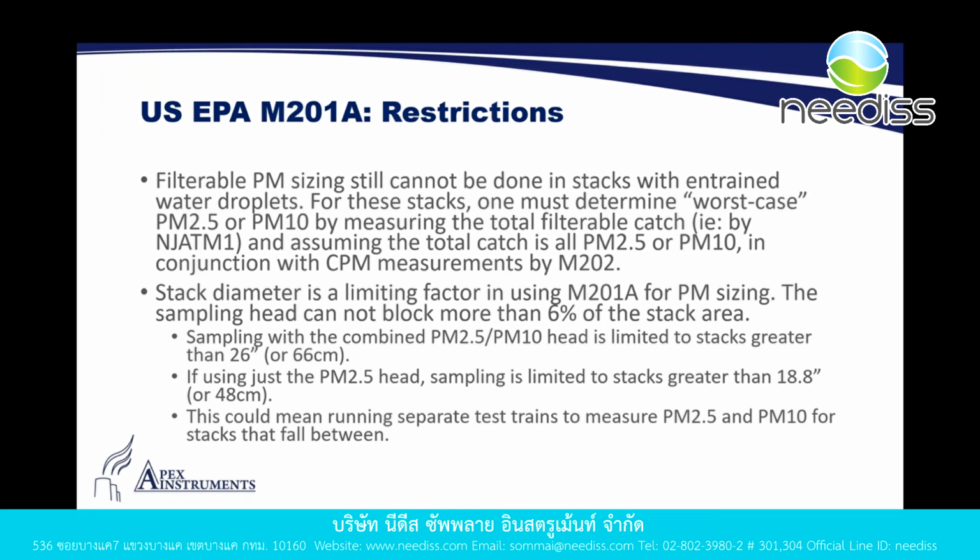And then just as a point of reference as well, if you had just the single PM2.5 or the single PM10 head, 6% of the stack area blockage would confine you to sampling stacks larger than 48 centimeters in diameter.